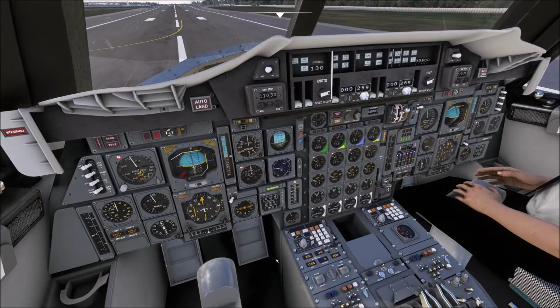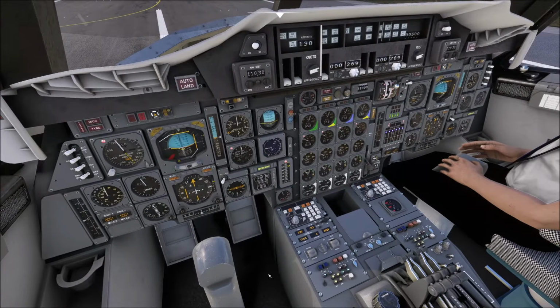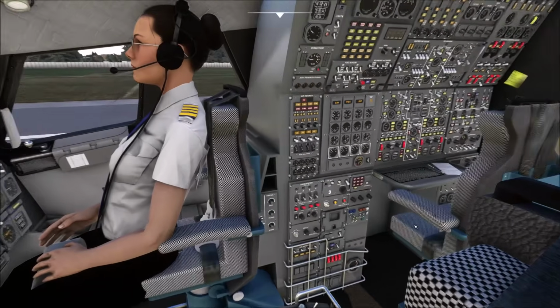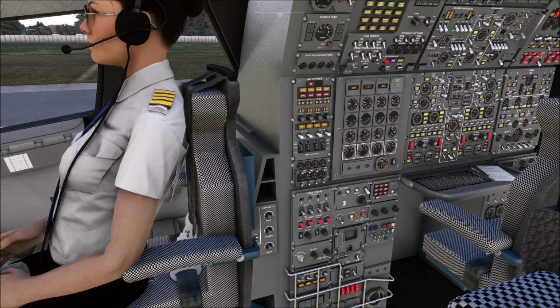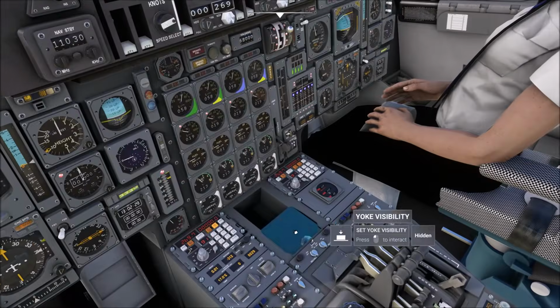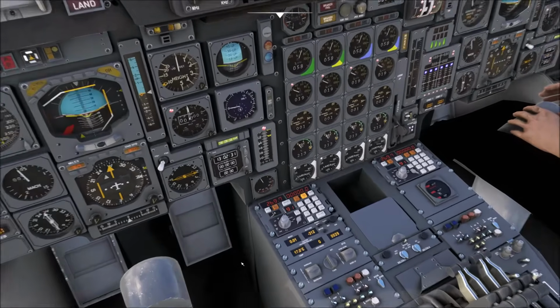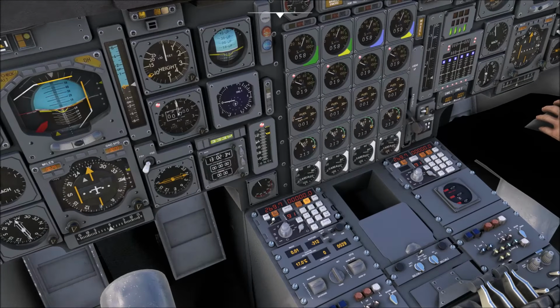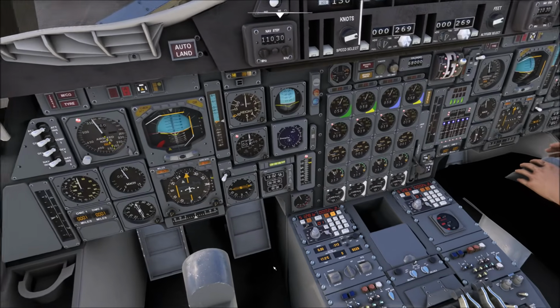So first things first. We need to get these active. The MCU for the INS is here. You simply switch to nav. And you'll see here now it's alive. And what you do is you hit remote on, loading flight plan loaded, remote off, switch to auto. It's now set from flight waypoint 1 to waypoint 2, showing up on the HSI. I normally set this to position, going from 0 to 1 there.